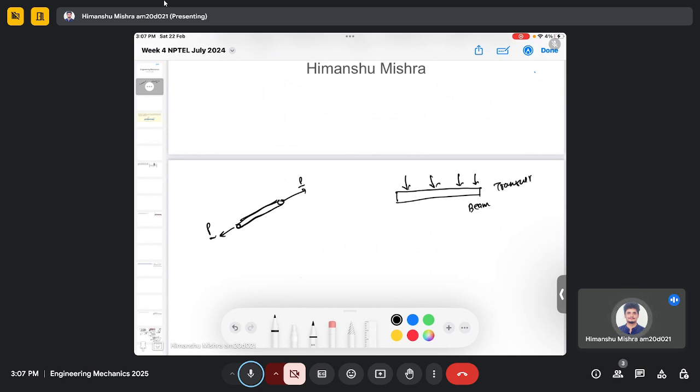Beams are a very integral component in engineering, and that's why it is really crucial to understand the basic concepts, like how forces are distributed across the beam and so on. One assumption that we will follow, which greatly simplifies the calculation, is that we consider all the calculation in 2D. That means we don't need to consider the width of the beam, at least in this course. So we will neglect the width of the beam, and therefore our analysis is mostly restricted to a two-dimensional domain.